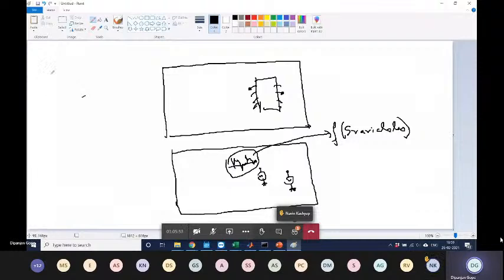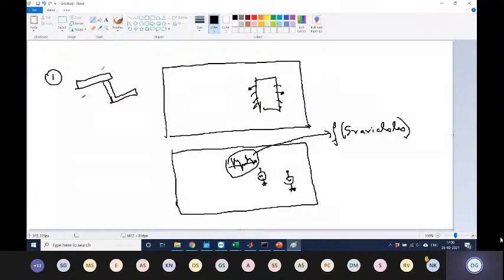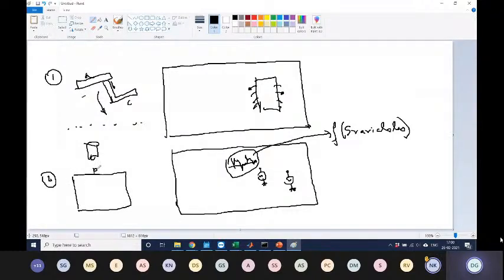What I have seen in literature is that, typically, the structures that we simulate, if you are able to parameterize the structure, that's very basic, right? You identify some parameters, solve for some, and keep the rest for predicting. It's typically used, for example, for via dimensions in PCBs, trace width, trace length, and all these different parameters. I've seen that work in literature. In fact, in our group itself, you're probably talking more about solving the matrix equation, like a PDE or an IE-based matrix equation, using some learning-based methods.